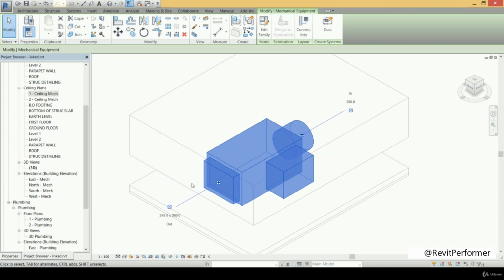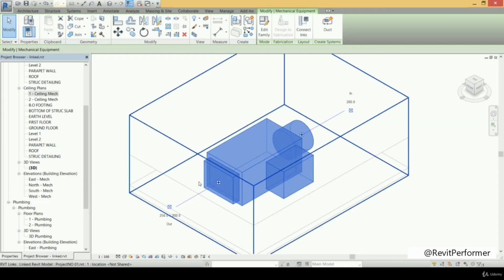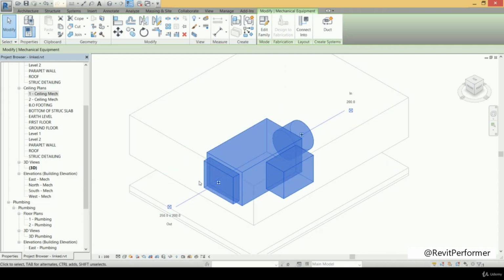It receives the air from its input, then it controls the amount that will flow out of it, as it has some dampers. This is because it's a variable air volume box, so the dampers control the amount of air flowing through it, and then it goes forward through the output to feed the branched ducts and to feed the zone we have. Very good.